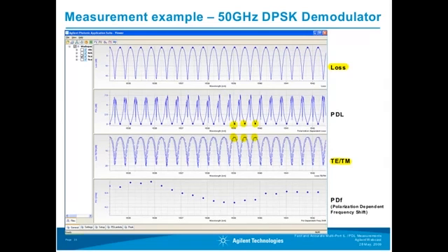So you would like to verify the polarization dependent frequency shift, and this is done by this software automatically. So for every channel, you see that we have here the wavelength shift obtained and displayed. And if you look precisely here, the wavelength shift here is in the order of 4.4 gigahertz, which is, as mentioned before, quite a large wavelength shift.